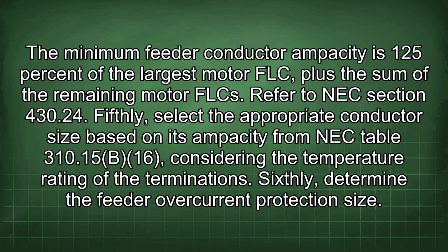The minimum feeder conductor ampacity is 125% of the largest motor FLC plus the sum of the remaining motor FLC. Refer to NEC section 430.24. Fifthly, select the appropriate conductor size based on its ampacity from NEC Table 310.15(B)(16), considering the temperature rating of the terminations.